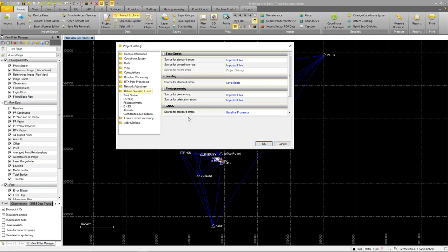Here we're rotating and transforming a set of observations so that they match between the control coordinates, and they are fundamentally different and basically incompatible with one another in some way. So you will have to choose whether you want to have a calibration or a network adjustment in your project. You can do a network adjustment and get an adjusted set of coordinate values that you use in another project to use as the control for a calibration if you choose.